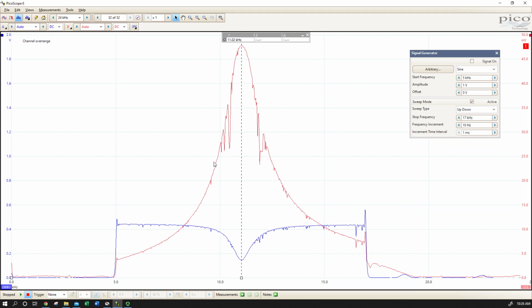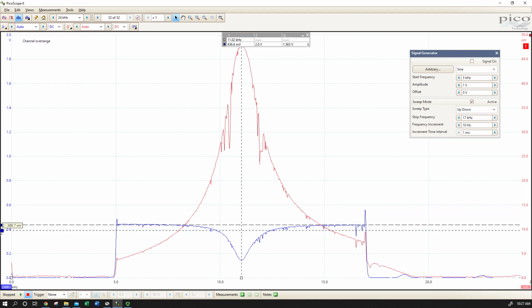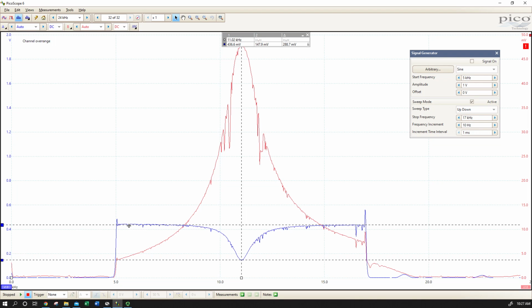We just used a frequency sweep, we let it collect some, and boom, there's our resonance peak. Something else that we can do is use the full circuit to measure bandwidth. We've got a good enough signal to do that. So for that, we would measure the amplitude of that peak using the baseline.